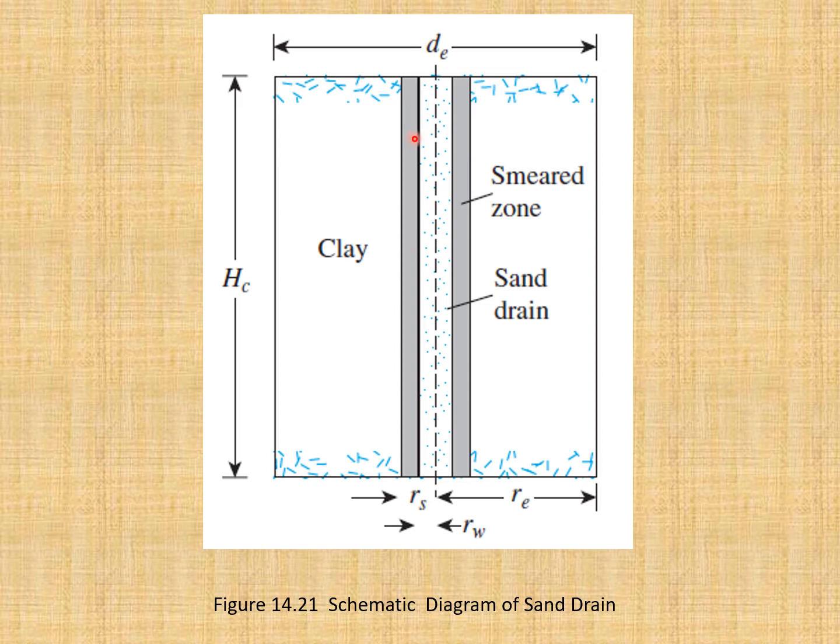So keep this in mind, that during the installation of the sand drain, disturbance of the soil adjacent to the drain, here and here, is likely to decrease its permeability and thus slow down the consolidation process. This effect is described as smear.